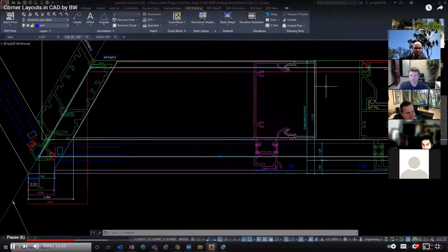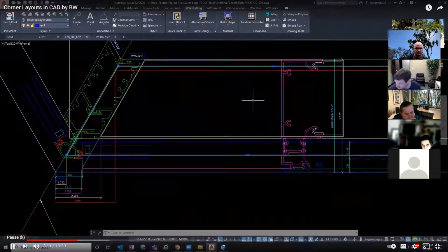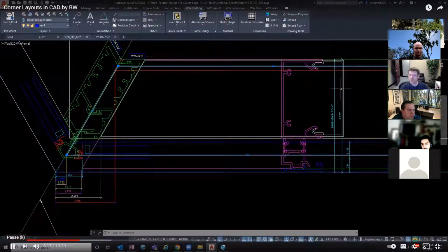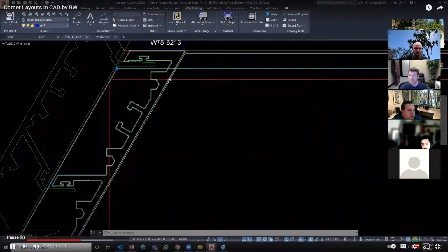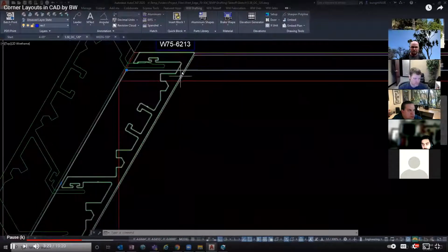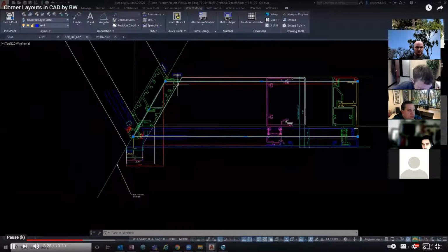We also have a deep head filler part. When they did the performance mock-up, it was determined that those needed to be undersized by 1/32 total so that the parts would be able to snap in. So I have a 1/64 offset from the line of the vertical.